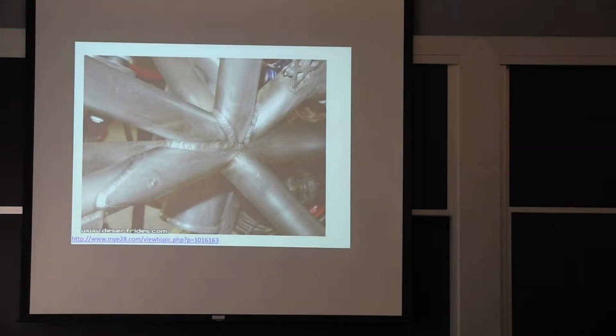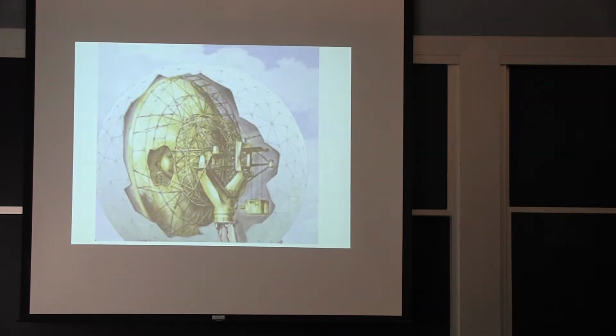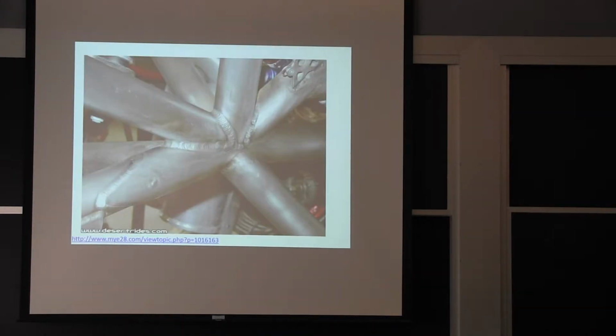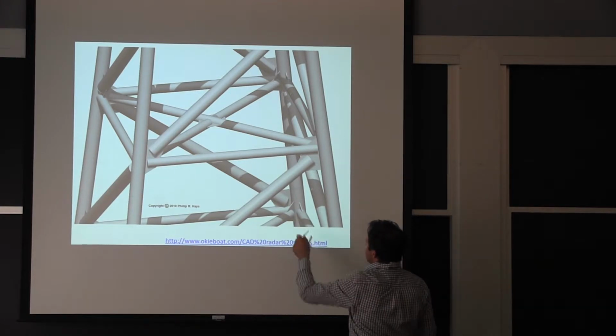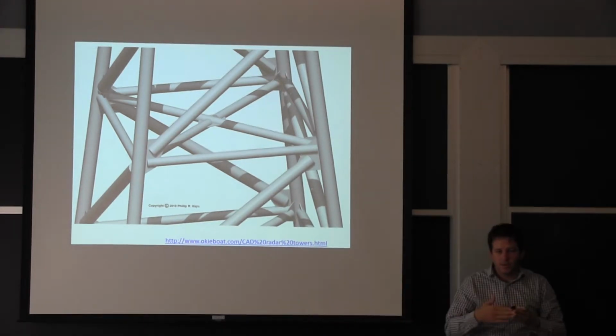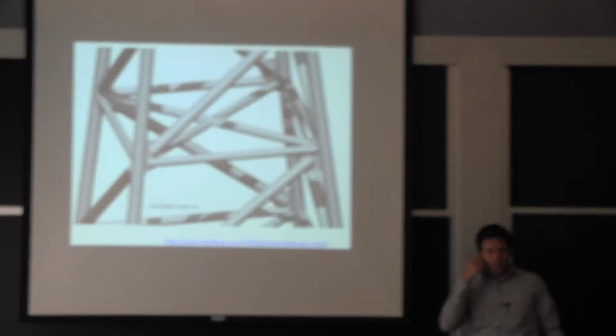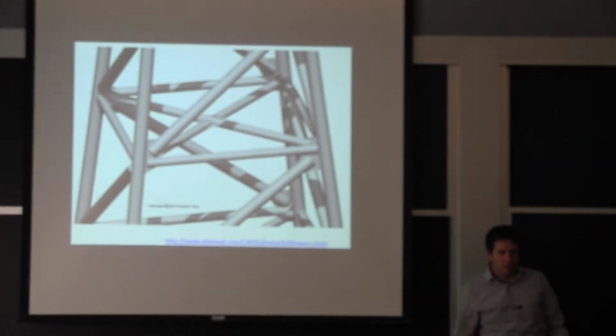Yeah, and it was a problem when they did this because you can size the members very large. A lot of the size of the design was based on stiffness. When it was coming down to some of the connections, there were a few between 2 plates. It's very nice to use plates because the plate allows you to load in shear, but you come into this situation where this plate needs to connect to something else, and eventually you have the plates connected to each other, and they are going to be in tension, one with respect to the other, and that's where the low allowable stress comes in.